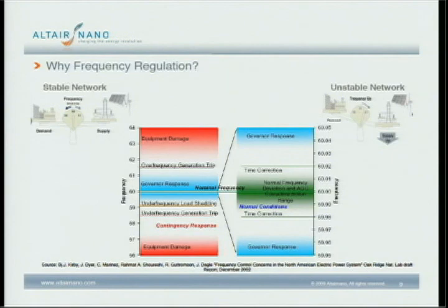As we zoom in on that, you see some typical AGC corrective action. Automatic generator control, that's the ISO watching over the system, automatically saying, wait a second, I need a little more power. They send out a signal; in California, they buy roughly 400 megawatts of regulation, up or down. The signal goes out, the generators pick up a little bit, 4 seconds later, we need a little more, the frequency is still deviating. Okay, now we've caught it, let's move it down. Let's take that 400 megawatts and bring it down to 350. Or let's actually bring the load all the way down to 200. And that's how they're controlling that 60 hertz signal.